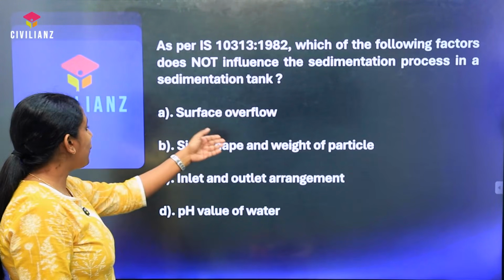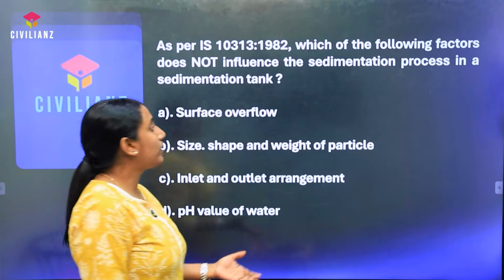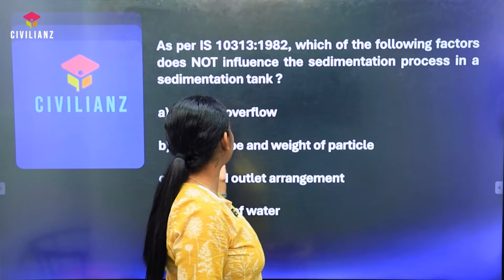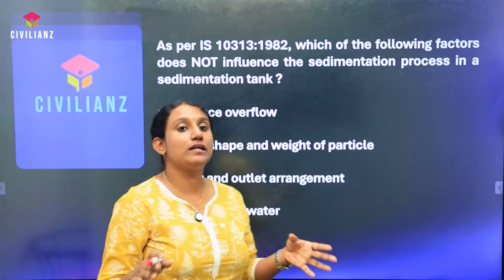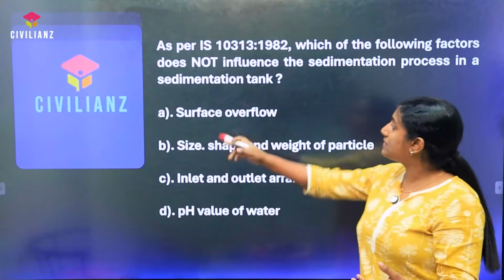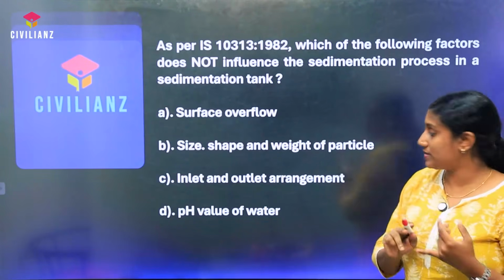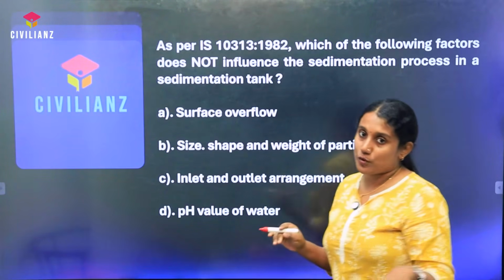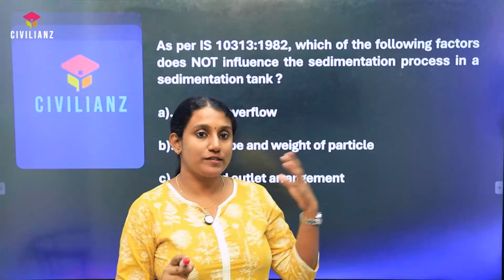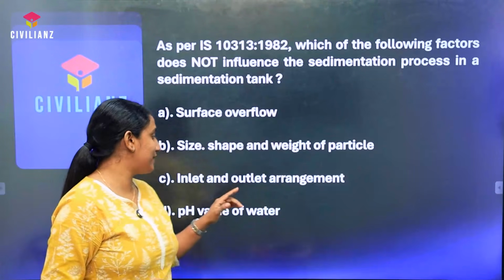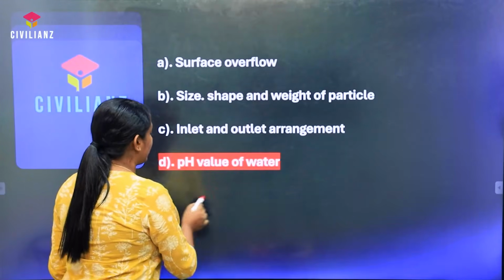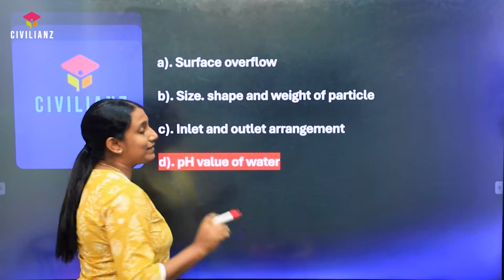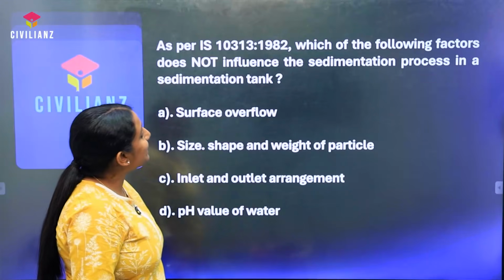Actually, surface overflow obviously depends upon our sedimentation process. And also size and shape of the particle, the weight of the particle obviously depend upon the sedimentation process. Inlet outlet arrangement also depends upon the sedimentation process. Only one condition we do not consider, pH value of water. This pH value of water we do not consider for the sedimentation process.